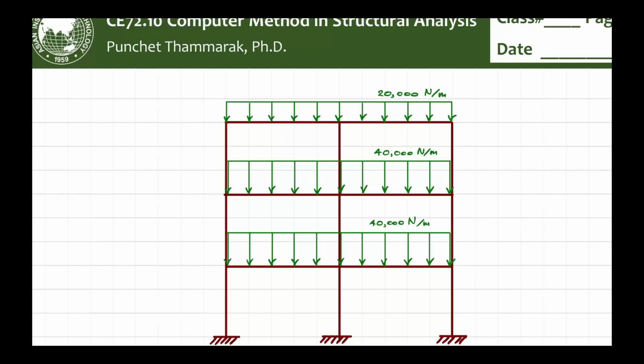So if you pour concrete during the daytime, like in the morning, concrete starts forming, turns into the plastic state after about 2 hours. Plastic state means, okay, it gets hardened, but it has no strength. So hardened, no strength, and then it suffers from the shrinkage that causes cracks, right? And then you have cracks all over your roof slab. The bigger the slab is, the more cracks, because of the more restraining effect, right?